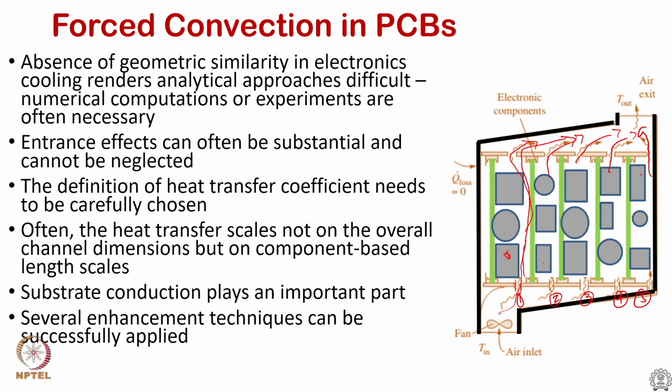This length is equal to this length, so that there is no flow distribution issue from a single fan, and on top of it we have to ensure that some PCBs need more airflow compared to the other PCBs. Those are also managed through these orifice sizes.